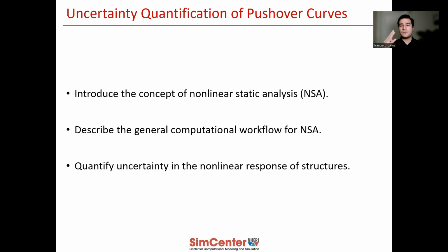So this module has three main learning objectives. We want to introduce the concept of nonlinear static analysis or pushover, and describe the general computational workflow to make a nonlinear static analysis using OpenSees, now using the Tcl interpretation as opposed to the OpenSeesPy interpretation that we have already used in a couple other modules here.